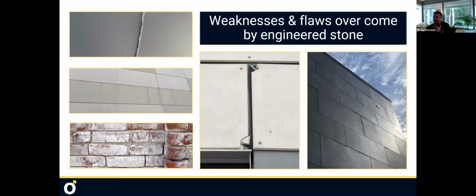All right. Again, engineered stone is not requiring that level because they don't pop corners, because they don't thermally and hygrothermically cycle the same as these submaterials. Okay. The one on the right is a very fun picture. Literally the furring is popping out of that high density fiber cement, ripping out like the movie Alien, which is kind of funny. It's only kind of funny because this was actually one of my projects in the Carolinas years ago. And it wasn't fun to fix, but that's a different story for a different time.